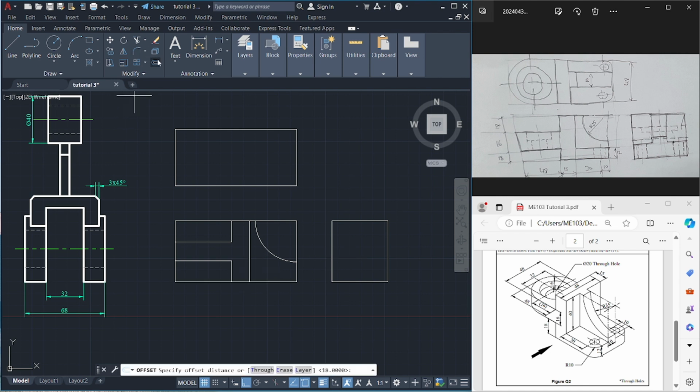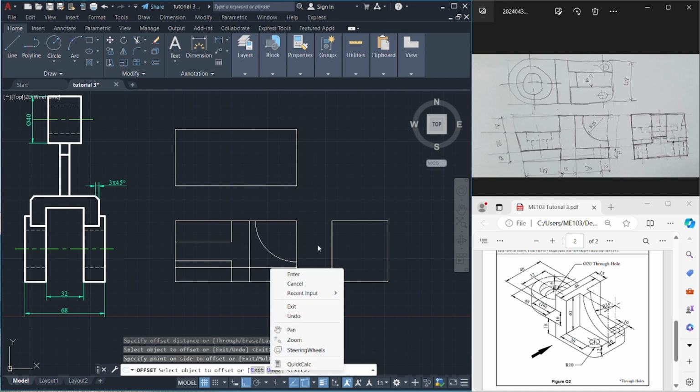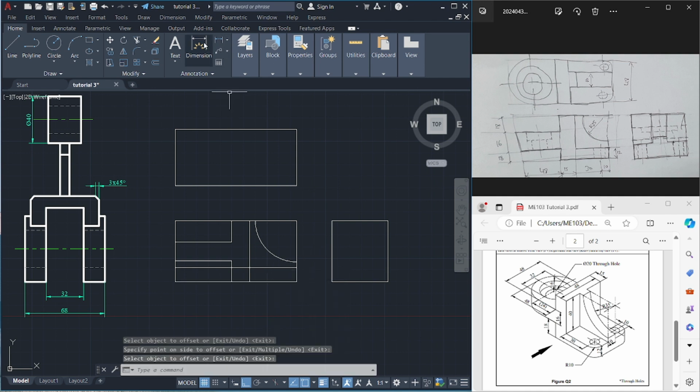I'll start with that one. It is 12 millimeters from below. So from here, 12 millimeters, and then I can trim that also. Boundaries to this line, and trim this part. So trim again, and this is not supposed to be there also. And I can reduce this one also now. I don't need this one. And this one also, I don't need these ones now.